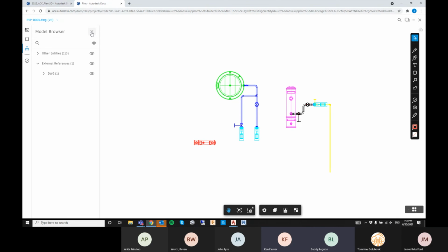Oh yeah, that's one of them other things that's an issue too, Jared, is that the viewer doesn't act like Navisworks when you turn off XREFs. When you tell Navisworks to not load XREFs, it doesn't work that way through this. When you save it out to an NWD file, it's still going to have the XREFs. Yeah, it ignores the switch that you've hit in the settings.